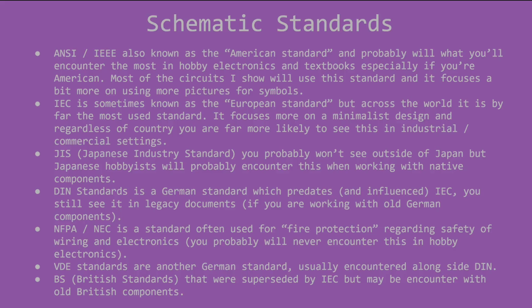All right, so what schematic standards are actually out there? Well, first is IEEE, also known as ANSI, and often referred to as the American standard. This is what you'll encounter by default in most of my videos, circuit simulators, textbooks, etc. It focuses a bit more on using pictures for symbols, but it's not extremely different from other standards such as IEC. IEC is sometimes called the European standard. It's actually probably the most used across the world outside the United States. It focuses on a bit of a cleaner and more minimalist design when possible. Although, again, the standard isn't so different from IEEE that you can't figure out one from the other.